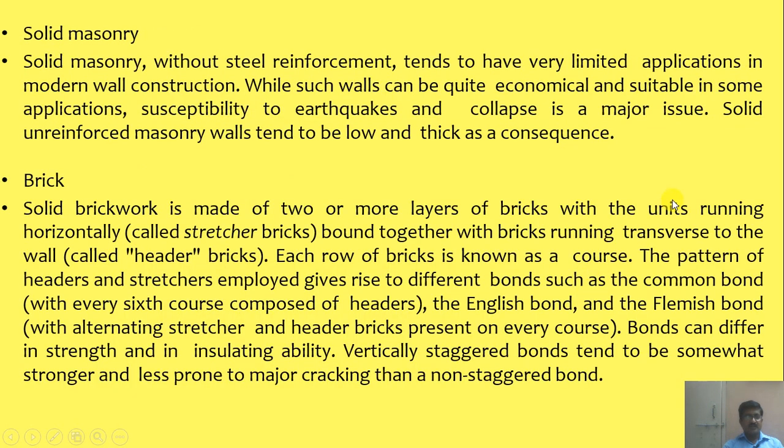Solid masonry and this brickwork that we are aware of, I will just revise. A solid masonry without reinforcement tends to have limited application in modern wall construction. While such walls can be economical and suitable to some applications, susceptibility to earthquakes and collapse is a major issue, so the solid unreinforced masonry walls tend to be low and thick as a consequence, right.